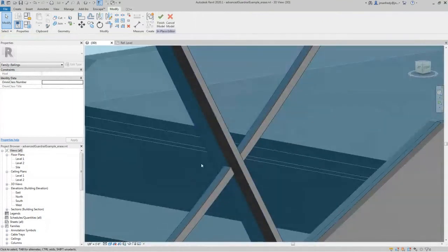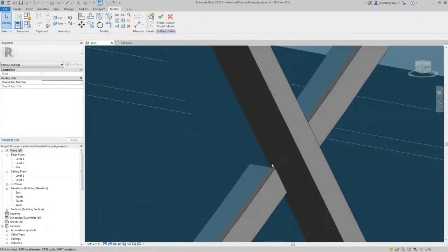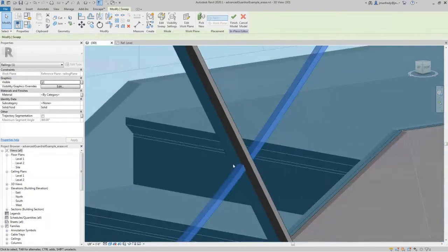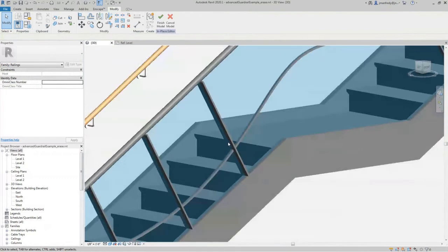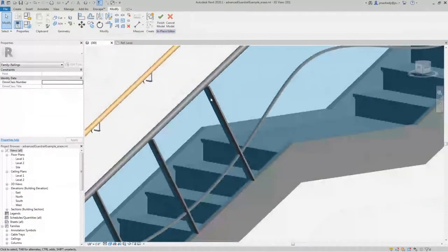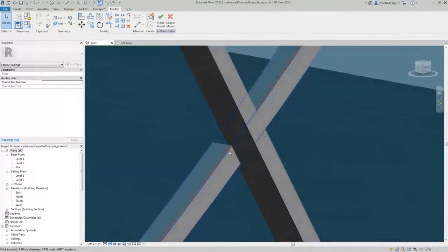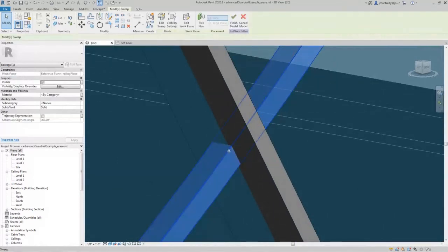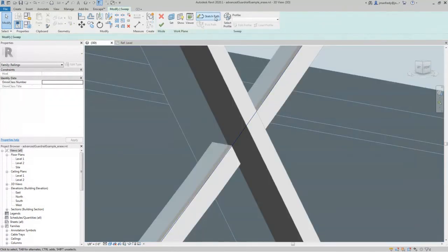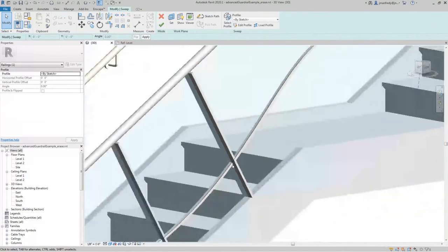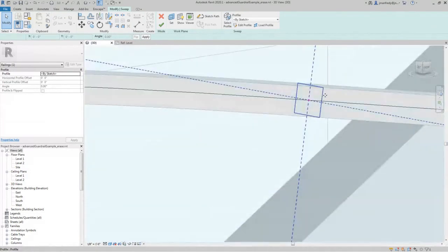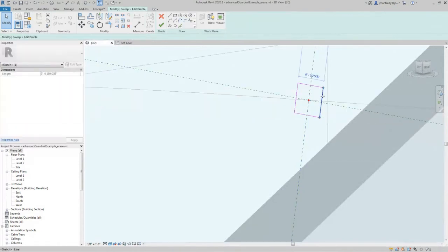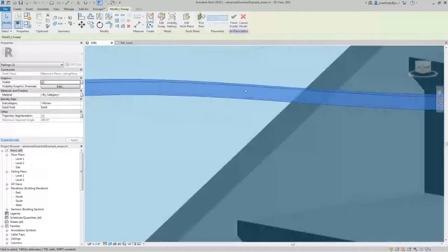And you see it's going right through the model in the location where I drew that sweep. And the glass is, I forget, I made it like a 1/4 inch thick or something. So you can manipulate this shape and move out this piece if you want it to stick out further and change its design, right? Edit the sweep, select the profile. The profile will show up right there. Make this edge, here's the profile. Select the profile, edit the profile, and I can make that grow a little bit more on one side, and you'll see what the effect is when I accept it.